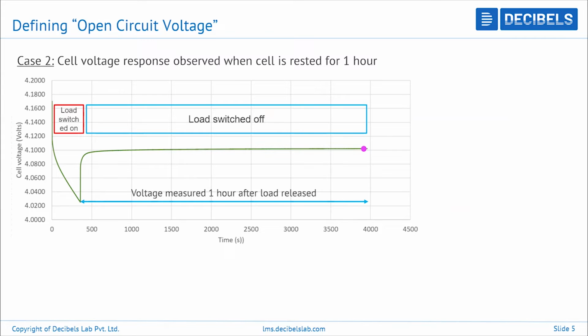So this value of 1 hour is the minimum, meaning to say it has to be rested for a minimum of 1 hour to observe steady state values. So what exactly do I mean by steady state is that, let's say that I consider this entire voltage region, only this, which is again under relaxation. At some point, you will notice that the voltage values start to become repetitive. From here onwards till about roughly here, you will notice that the voltage value is increasing. But from here to here, you will notice that they pretty much become constant or near constant.